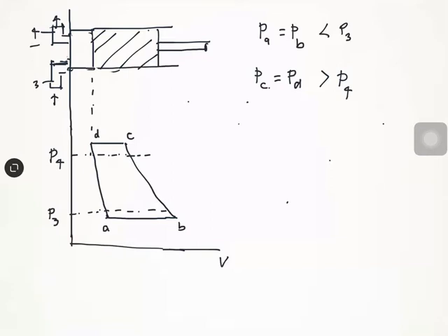Because of heat exchange between the vapor and the cylinder walls, the thermodynamic state of the vapor at position A may be different from that at position B, and the state at position C may be different from that at position D. At positions B, C, and D, we will assume the thermodynamic state of the vapor in the cylinder to be uniform.